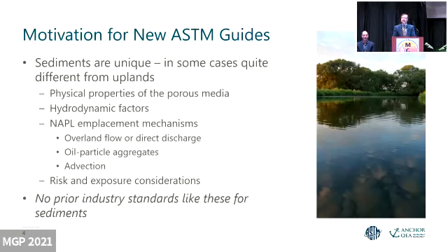Sediments are unique. For the past couple of decades, there has been an evolving and refined practice in evaluating NAPL mobility in upland settings. But sediments are different from uplands in a couple of key ways. First of all, the physical properties of sediments are different from the materials under uplands that have been compressed under an unsaturated vadose zone.